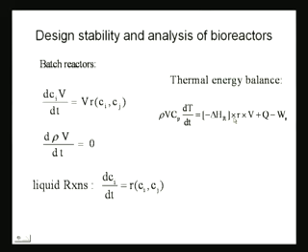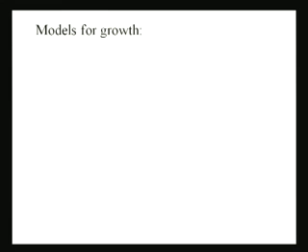So we had the reaction rate over here, R, and what should be the reaction rate? Now as I said, these are very basic equations, and you can use them for all kinds of reactions that happen in bioreactors, but we are specifically interested in growth reactions, and we will use today the very simplest kinetics of growth, Monod kinetics. Through much of this chapter we are going to use Monod kinetics, but you should be ready to deal with other kinds of kinetics, because in the test that's what I might give you, with inhibition, like we did with inhibition, with multiple substrates. It gets a lot more complicated, the whole analysis, and you should be ready to do those kinds of things, I tell you in advance.